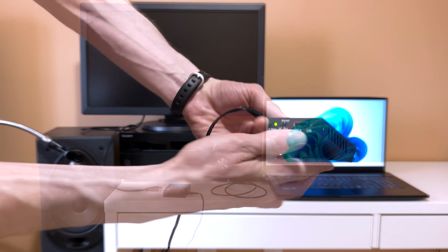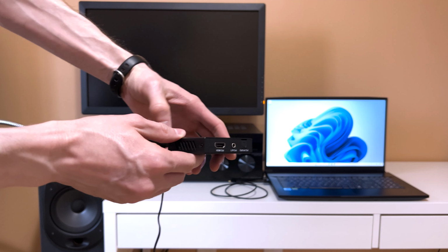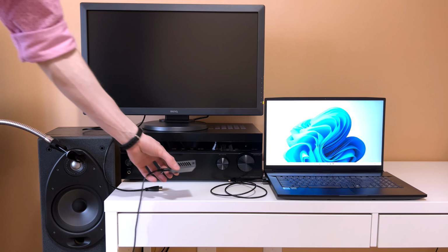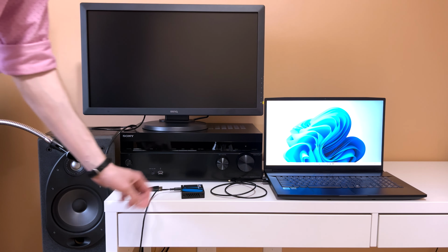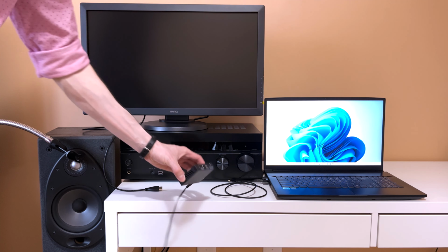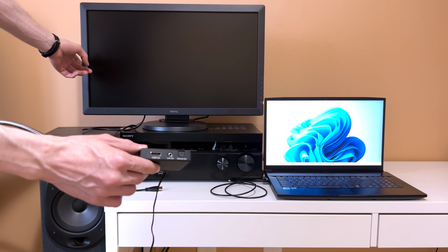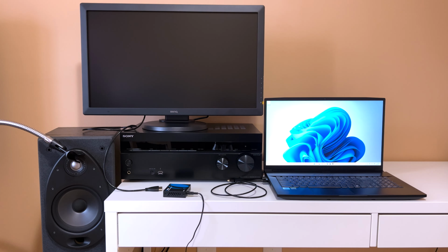This software toolkit makes use of inexpensive consumer electronics, like this HDMI audio extractor, to accurately measure audio latency. It works by using any analog stereo audio input on your computer, such as the microphone port, to record the analog output of the audio extractor and the audio output of the device under test. It then measures the time offset between the two analog audio sources.